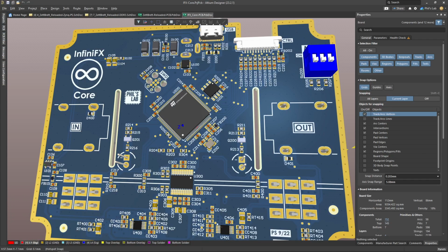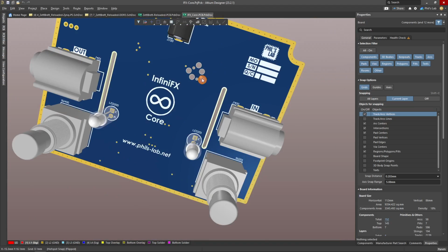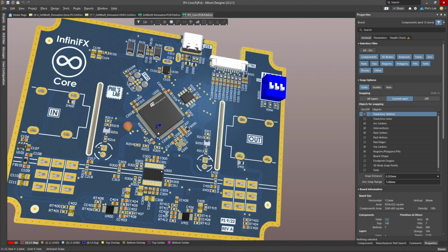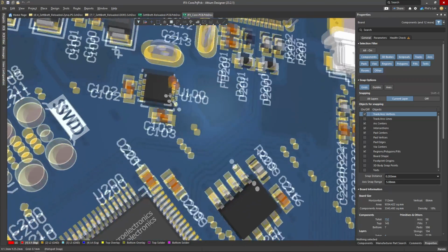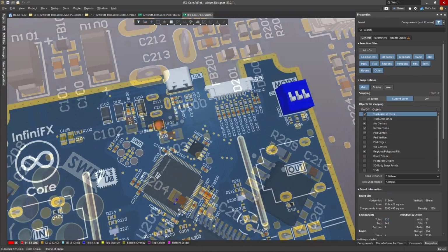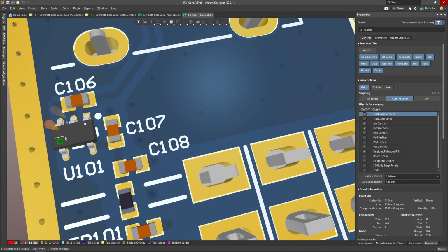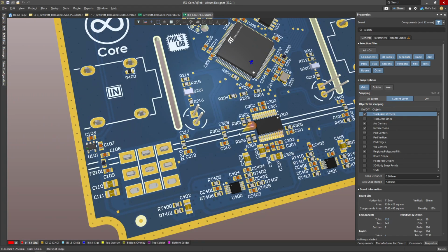A design we saw earlier, which I showed you a picture of after it had been assembled and manufactured, is this DSP guitar pedal I designed a little while back. Due to noise requirements, and because I don't actually have a very high input-output voltage differential, I went with LDO regulators. Also for simplicity, and of course noise requirements due to this being a mixed signal system. I have one of the LDOs at the top here with a certain package, and this feeds the digital section, and far away on the left-hand side I have this smaller LDO which then feeds my analog section.